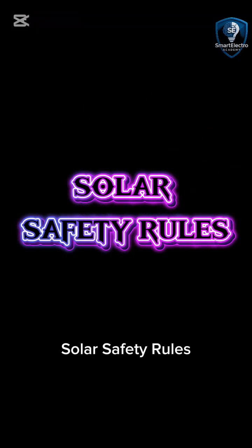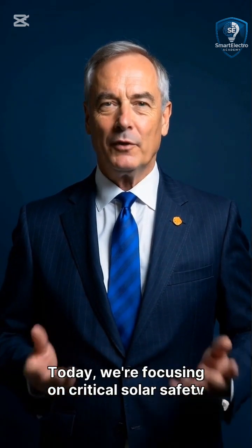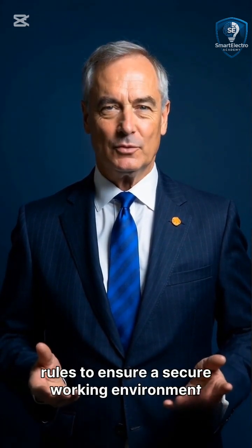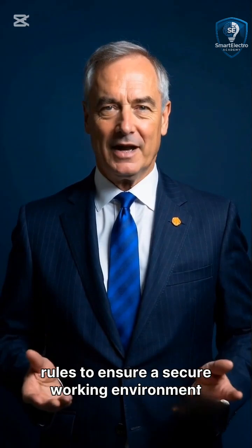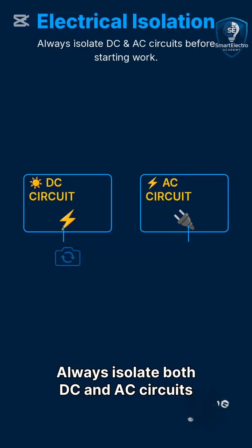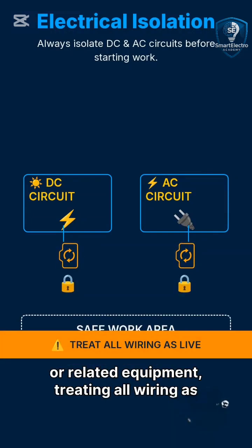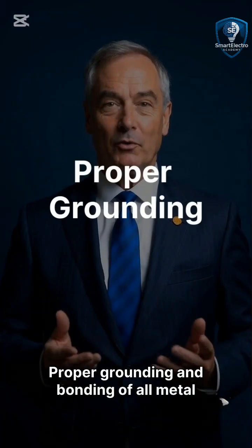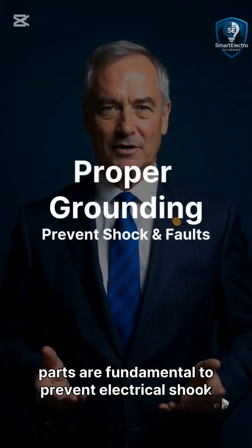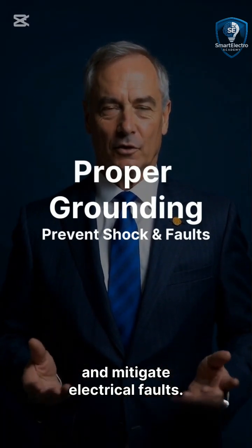Solar safety rules. Welcome, professionals. Today, we're focusing on critical solar safety rules to ensure a secure working environment for everyone involved in solar panel installations and maintenance. Always isolate both DC and AC circuits before starting any work on solar panels or related equipment, treating all wiring as live. Proper grounding and bonding of all metal parts are fundamental to prevent electrical shock and mitigate electrical faults.